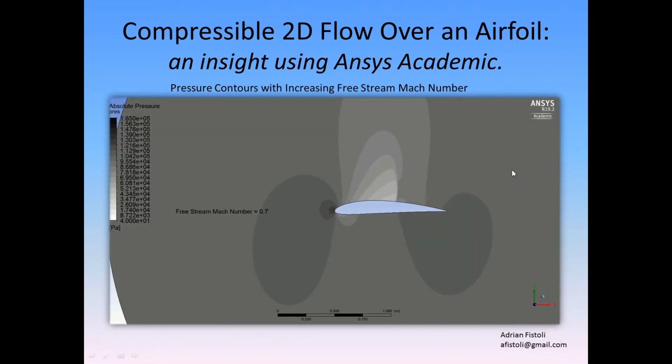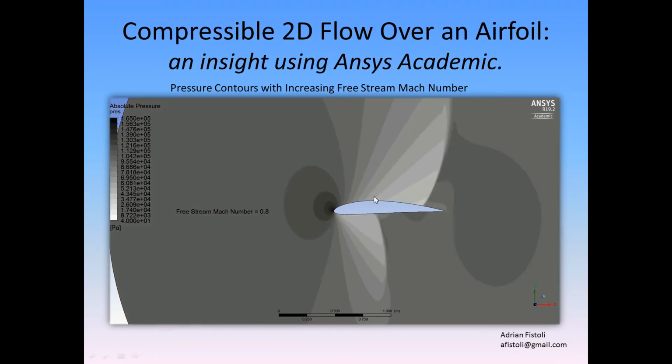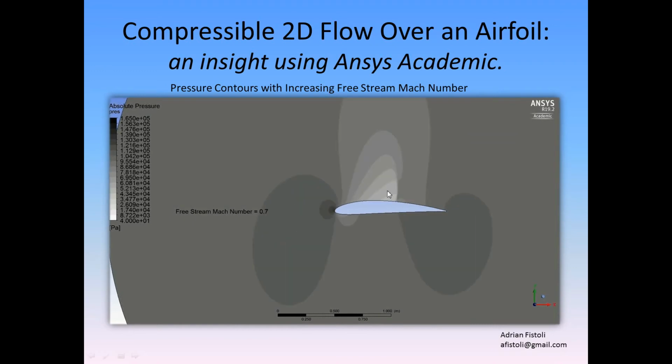If we focus our attention on the upper surface, we see that the pressure keeps on dropping as the Mach number increases, explaining the change in lift as we expected. You may also notice that for Mach number of 0.7 there is a somewhat low strength shock wave, and that for Mach number of 0.8 we have distinguishing shock waves manifested by a rapid change in pressure.